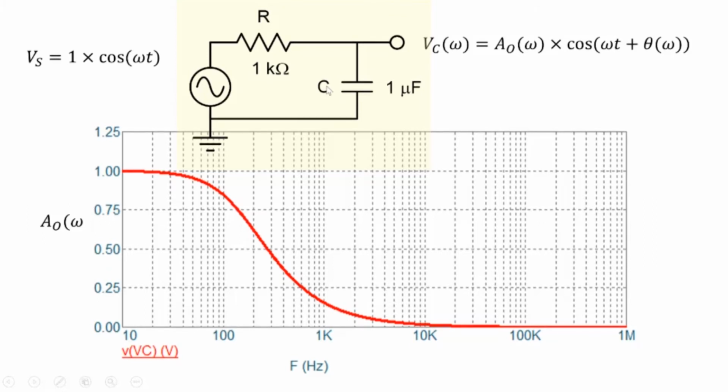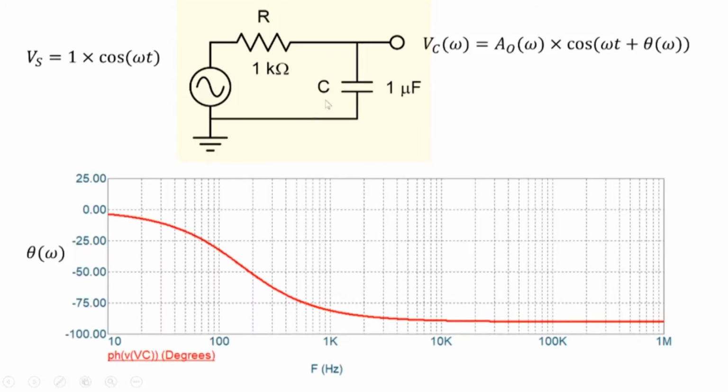In the time domain, we could see that the circuit was charging. When we apply a step voltage, it was charging towards a constant value, and when we remove the voltage here, it would discharge. But this one is providing us with additional insight that this circuit acts like a low-pass filter here. And the phase value, if you go and look at the other part, the phase value starts from 0 and then eventually goes towards 90-degree phase here, right?